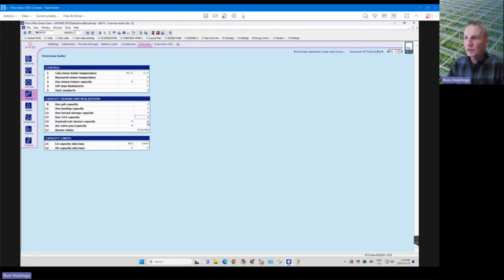So then we convert the kilowatts. You've got the kilowatt demand, between 800 and 5,000 kilowatts that this boiler has capacity for. If the flame is at lowest flame, we're going to say a valve position of 0%, and it's going to be giving out 800 kilowatts.